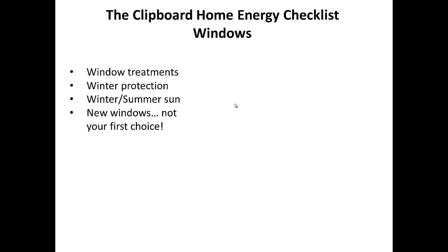I should also say that another benefit of an energy auditor that's professionally trained is that they're also trained about the safety of furnaces. In the first paragraph on the home energy checklist, at the very top, it says that it's very hard to do, but if you've got an old furnace and you work really hard on making your house airtight, you can make your home dangerously unhealthy, because you're not getting enough fresh air into the home. In the homes that I built, I made them extremely airtight, and we actually used a special device called an air-to-air heat exchanger, which helped bring in cold air from the outside, but it preheated it with the stale air that's being exhausted.